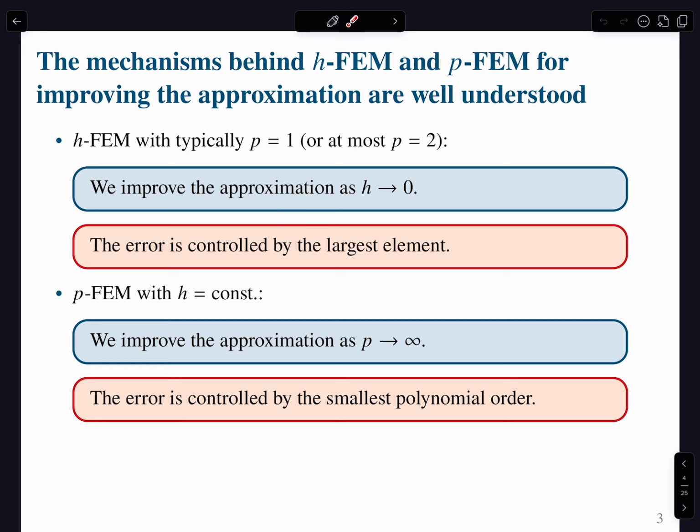But obviously, if you now have your mesh fixed and you increase the polynomial interpolation order, that doesn't necessarily have to be the case. We can actually keep our geometry to a lower order, in which case this formulation was called subparametric, right? So remember, we always look at the geometry to see whether it is subparametric or superparametric, or isoparametric.